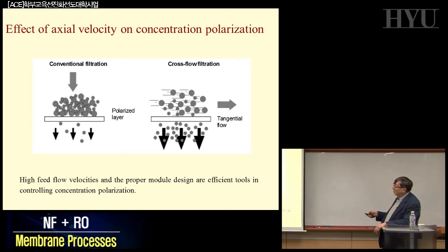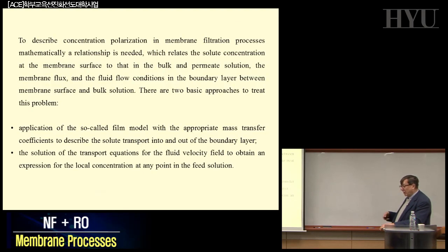But today, all the membrane systems are always characterized by very high tangential flow. I told you this can be 5 meters per second, 3 meters per second, and more than this. High turbulence promoters are always present in this situation. If you now want to predict and analyze what is happening to the concentration profile, it is not so easy, because all these parameters are changing with time, changing with concentration, etc. So if you make the real flow dynamic analysis, it's not easy to integrate your equation.